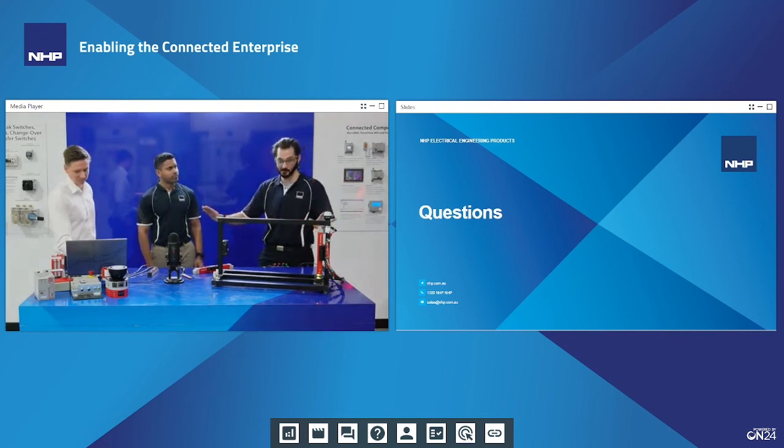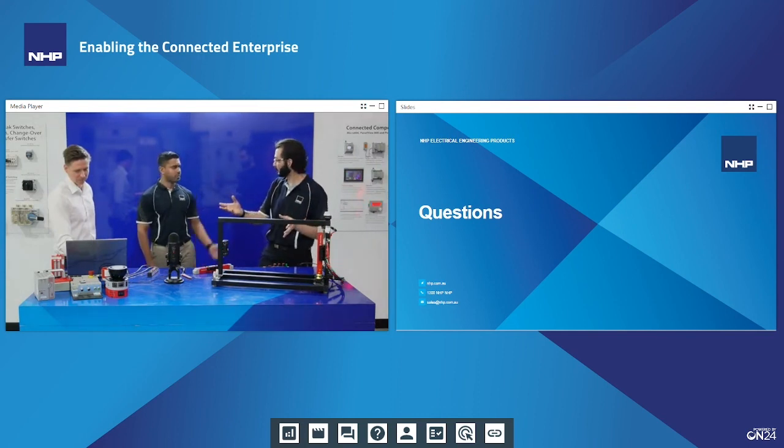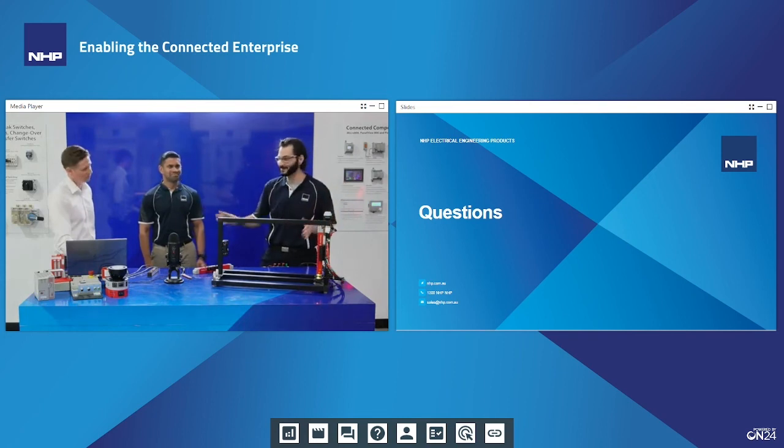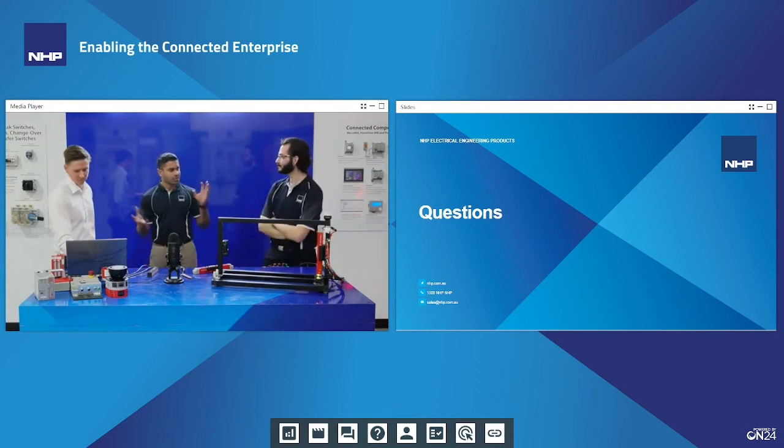You don't care what's in it. That's the whole principle of it, that the protocol is what's safety rated. The protocol travels over whatever media, any sort of switches, routers, gateways, hubs, if you're that old. It doesn't actually matter. It's completely black. You put your blinkers on, you don't look at it. So it's just the two devices at the end that need to be able to encapsulate and decapsulate those. Yeah, exactly.